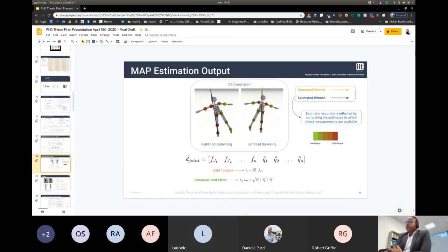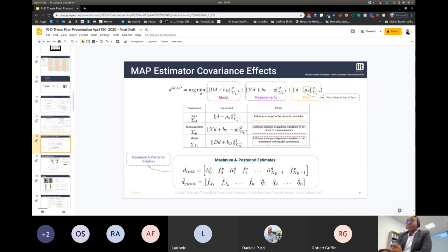One thing is we are not really confident about the joint torque estimation we are doing, that it is precisely what one would expect from rigid body modeling, because we didn't do any benchmarking for that. So maybe looking at the joint torque estimates, we can check more about what you're stating. As far as the current approach, we are just trying to align the measurements for the feet ranges, which we are confident about, to match the estimates of the feet ranges. And we are also matching the measurements from the accelerometers to the linked linear accelerations. So there could be a problem in the estimates for other variables which we cannot directly measure and compare.